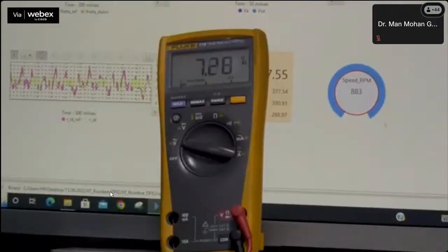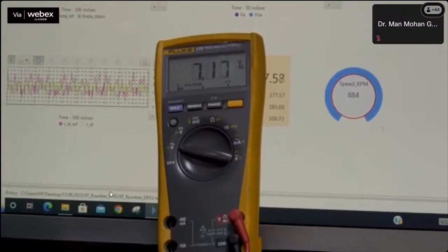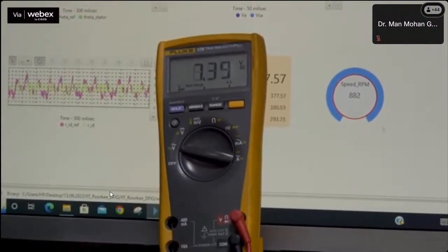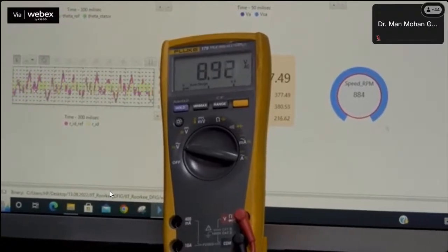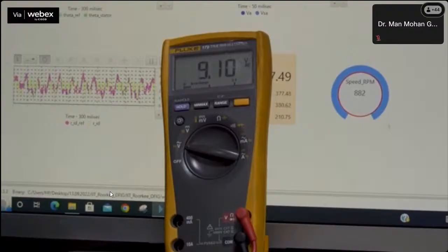After voltage gets matched in the software, then we check the contactor of the grid side and stator side and ensure that the voltage across the contactor in multimeter is less than 20 volt. Here we are getting a value of less than 10 volt across all 3 phases.